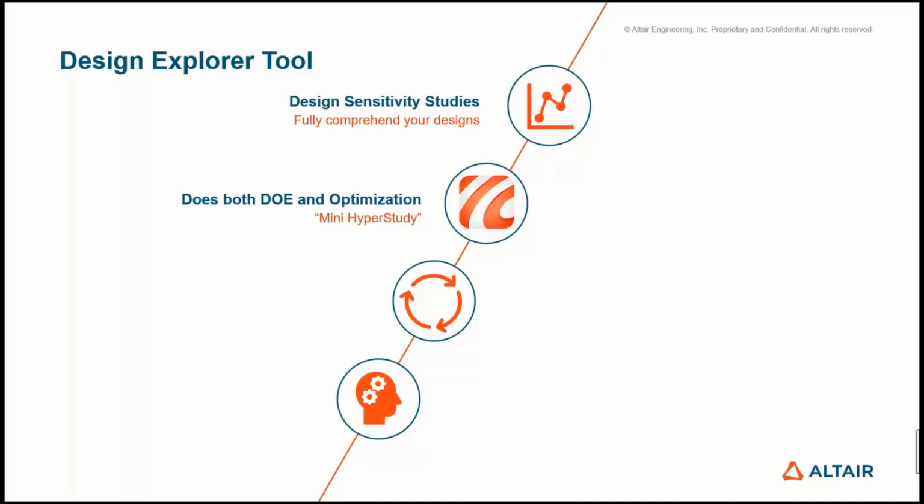So if you've done your Design Exploration study in HyperWorks, and you did want to take it further and conduct even more data mining studies with it, such as a stochastic study, you can actually take this file out of HyperWorks and open it in HyperStudy 2. You have an end-to-end workflow, so everything can be done in one GUI. From where you bring your CAD in, you mesh it up, you set it up for an analysis, you can then take it straight through into a DOE.